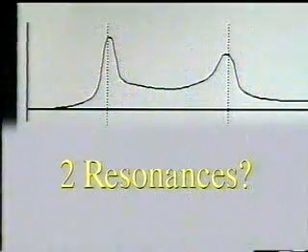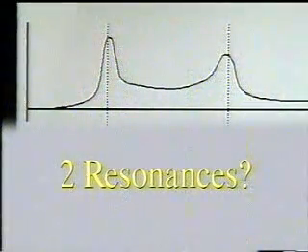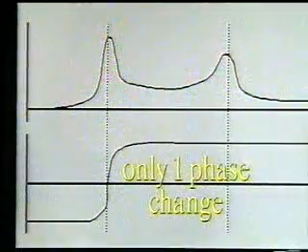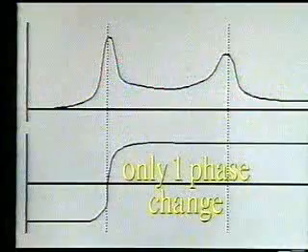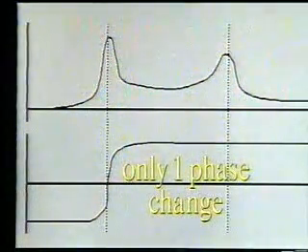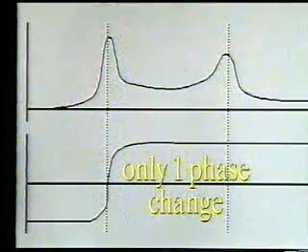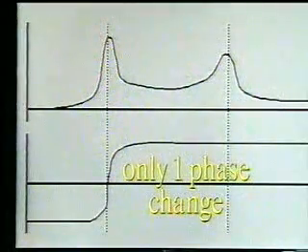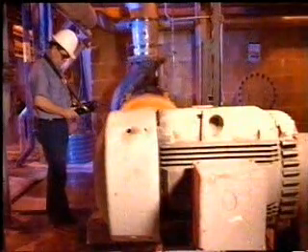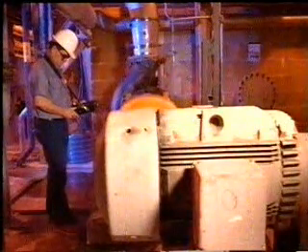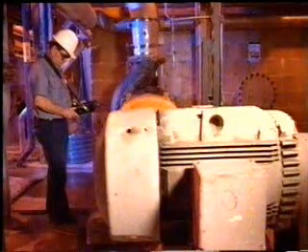This coast down plot has two high areas of vibration that at first seem to indicate there are two resonances. However, when viewing the phase plot, the phase changed at one of the high amplitudes, but not the other. Without a phase change, the machine did not go through a resonance. The high vibration at this frequency is from some other source. In areas where multiple machines are running, the high vibration could actually be from another machine. In this example, the high vibration is from a severe unbalanced condition in a nearby machine.